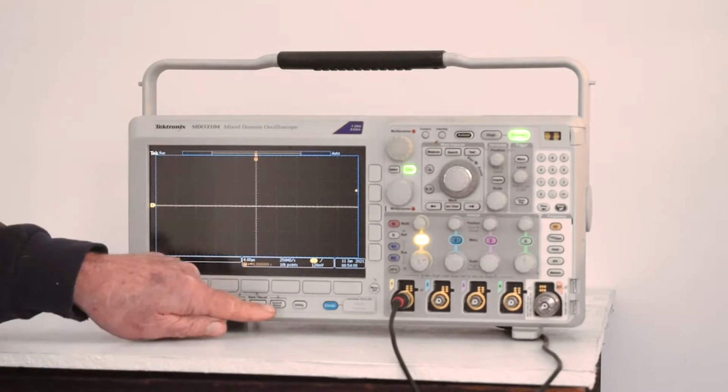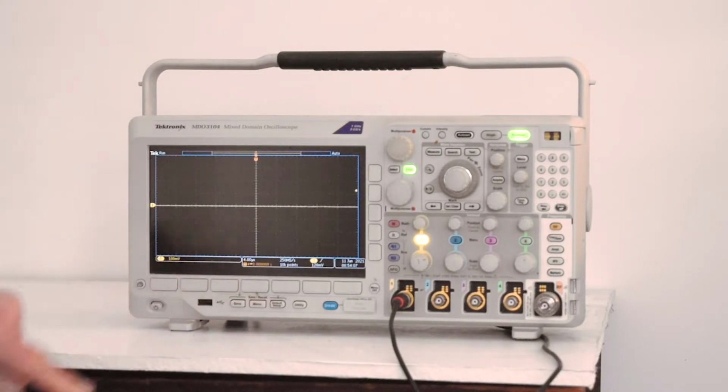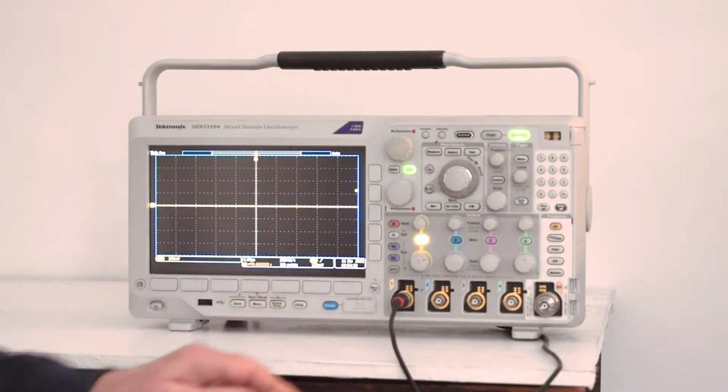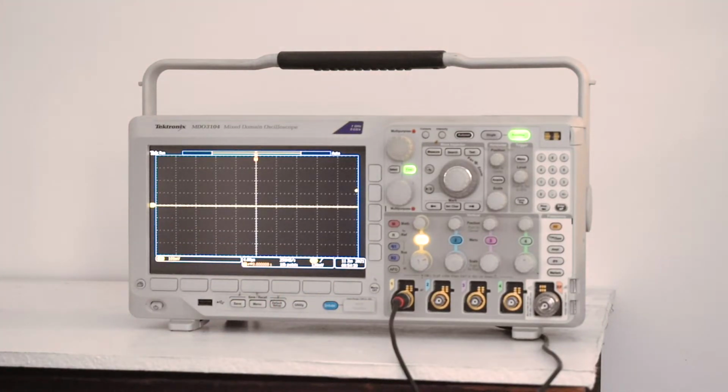Default setup is activated by pressing the small button below the middle of the screen. It restores the oscilloscope default settings, allowing the user to start with a blank slate, so to speak. You would expect this to happen whenever you power down the instrument, but that is not the case. Even unplugging the instrument does not default it, which means that at the start of the next work session, or in the event of a power outage, you can continue where you left off.